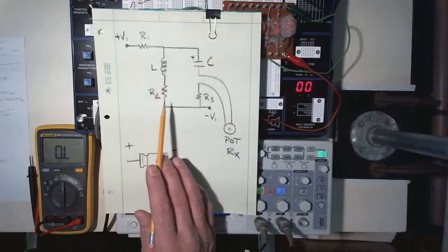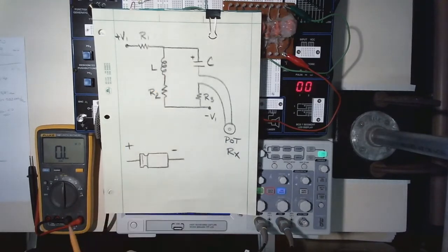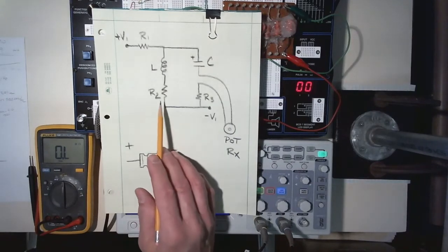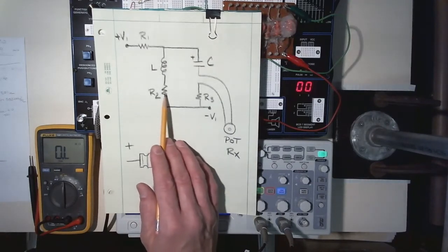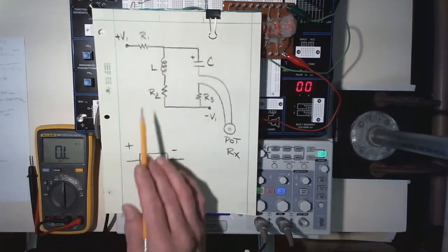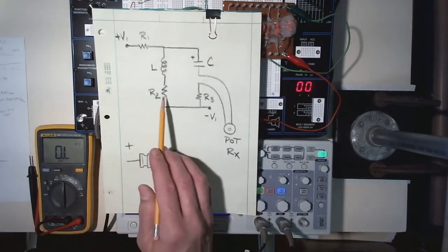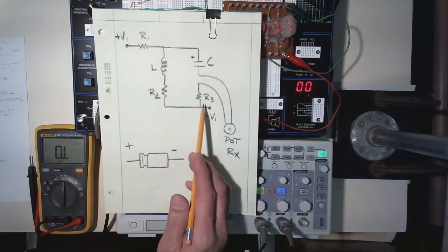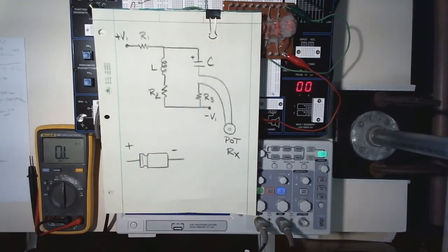The inductor, we're going to be at a half a Henry, 500 millihenries, and we'll just take that at face value. And then R2 is 100 ohms, and that's mainly a place to put all of the internal resistance of that inductor there, and we'll measure that so that we can deal with that also. And finally this R3, 100 ohms there, and we'll measure that.